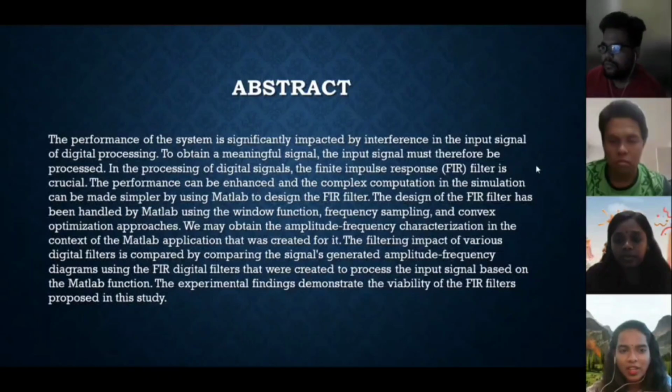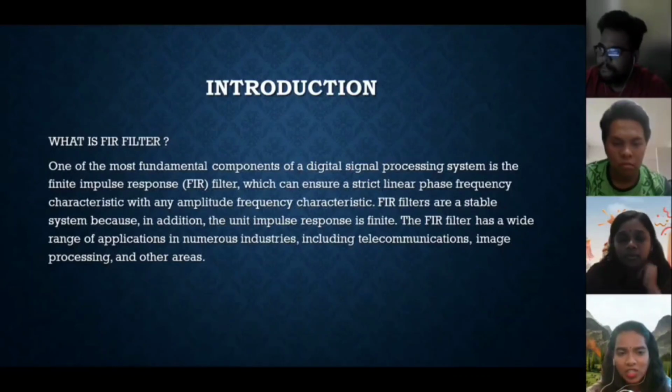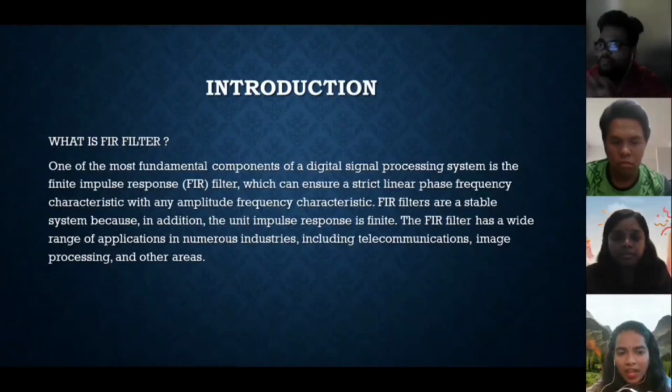Next is the introduction. What is an FIR filter? One of the most fundamental components of a digital signal processing system is the finite impulse response (FIR) filter, which can ensure a strict linear phase frequency characteristic with any amplitude frequency characteristic. FIR filters are a stable system because, in addition, the unit impulse response is finite. The FIR filter has a wide range of applications in numerous industries, including telecommunication, image processing, and other areas.